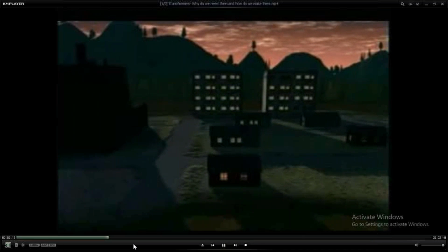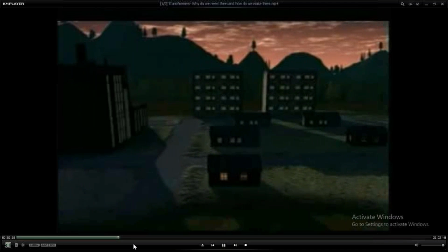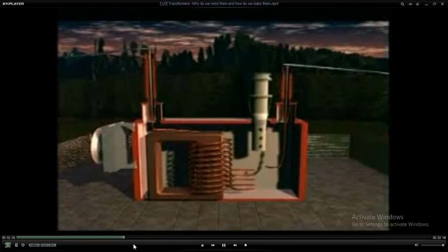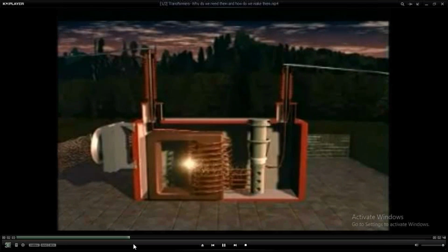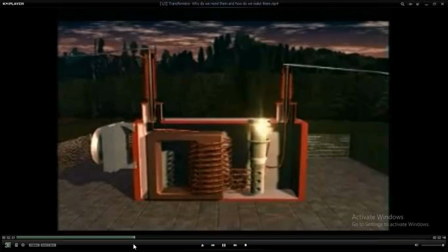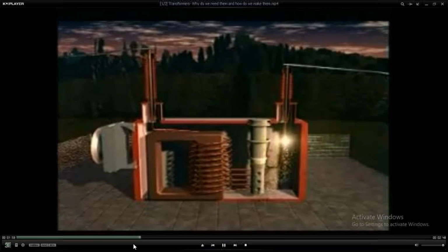From the power transformer, the electricity runs through the distribution network to reach small substations, where the voltage level is further reduced to low voltage to directly supply lights and motors. As the load increases, the power losses on the line are also increasing. Therefore, we need to adjust continuously the voltage level by changing the number of turns on the winding. The tap changer maintains a stable voltage level as the load changes during the day.